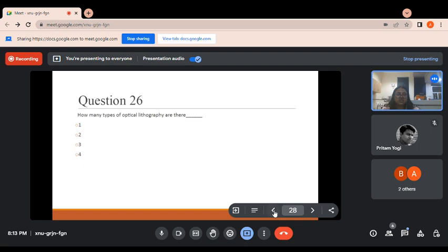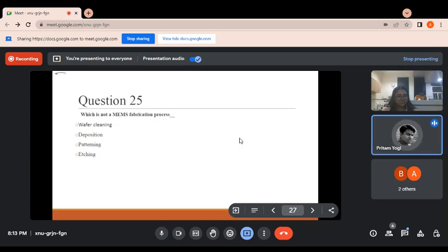Here we can discuss the cleaning process. Do you have an idea what type of cleaning process is used? RCA cleaning. Yes, RCA and another. The process that we generally use in the lab is not RCA. That is a simple process with three steps, where we use acetone, IPA, and Piranha solution.